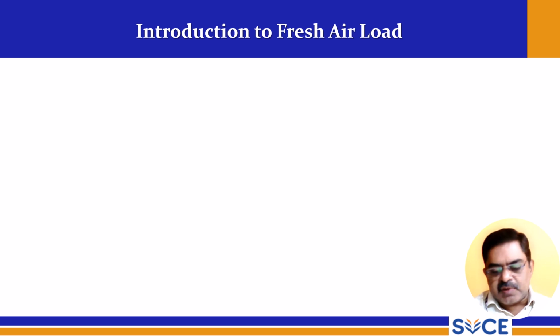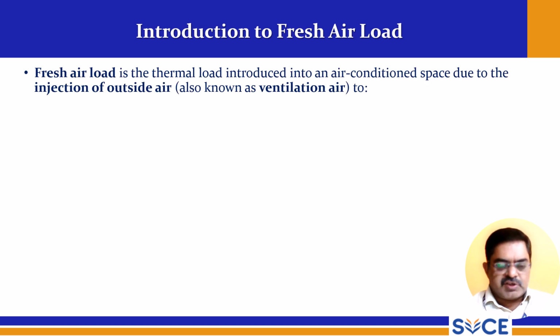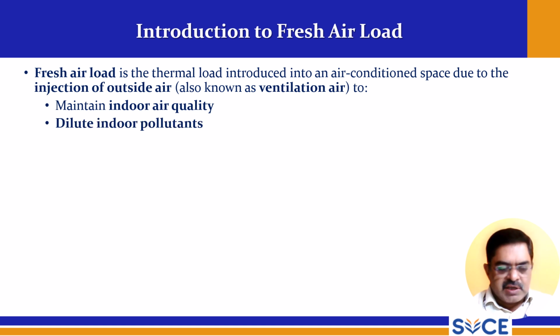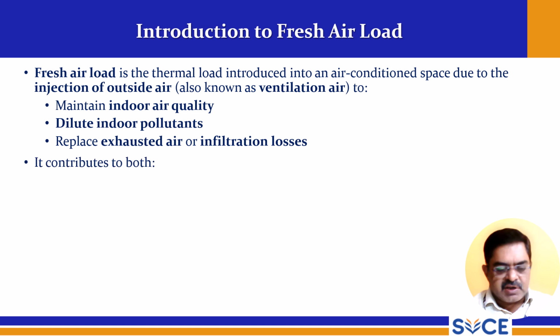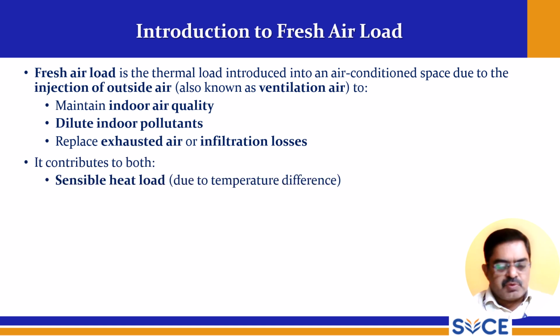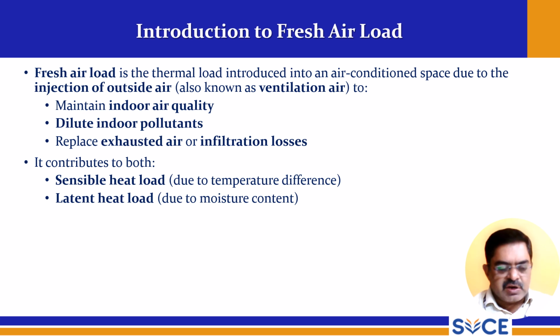So the next topic in this sub session is fresh air load. Fresh air load is the thermal load introduced into an air conditioned space due to the injection of outside air. It is also known as ventilation air, to maintain indoor air quality, dilute indoor pollutants, and replace exhausted air or infiltration losses. It contributes to both sensible heat load due to temperature difference, and latent heat load due to moisture content.